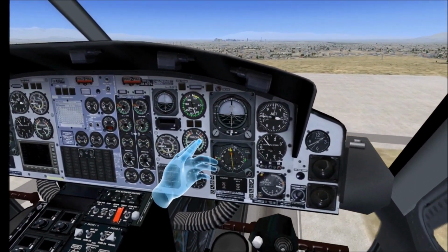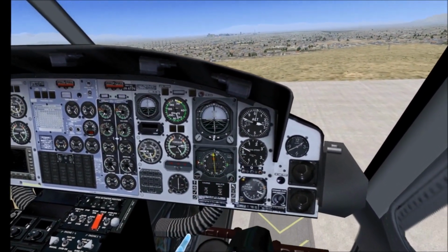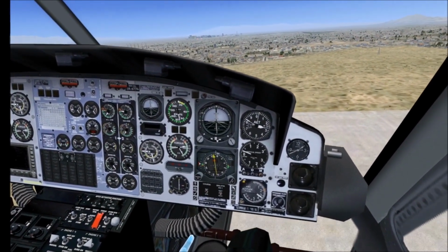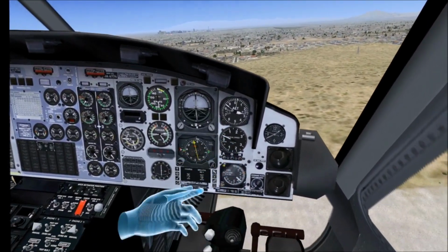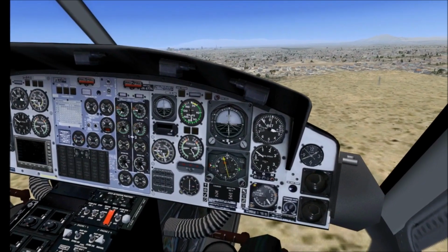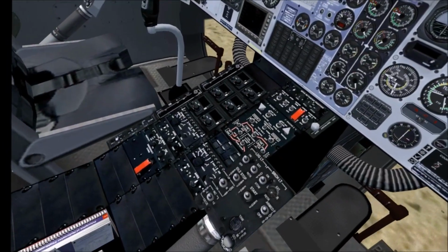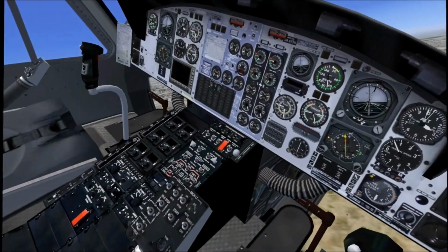Torque's right where we want it to be. I zoomed up a little bit, but it kind of settled right at 500 feet. Right at 500 feet per minute. So, yeah, I'm surprised, but I'll call that good. And this fluctuation is because I'm messing with the cyclic here, and I'm in a little bit of a turn. But 70 knots, that's good. It's settling right around 500 feet. That's plus 100 feet per minute. I'll take it. We can call that realistic.